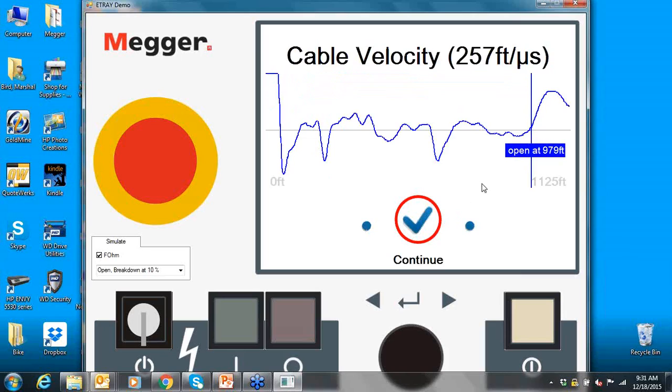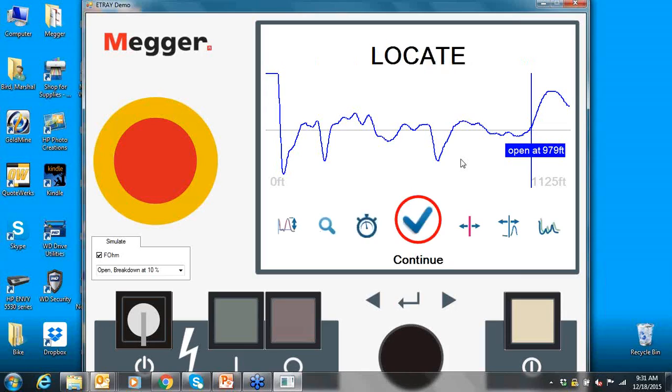So whatever your radar is set at, on short length cables you're going to be relatively close without changing your propagation velocity. But if you want to be accurate, you can go in and manually adjust it. You can pick off a chart. The most accurate way to set propagation velocity is for the exact type of cable that you're measuring. Someone's gone out and taken a known length of that cable and has made their radar match that known length, and that tells you exactly what the propagation velocity is.